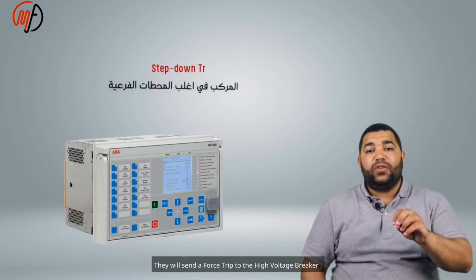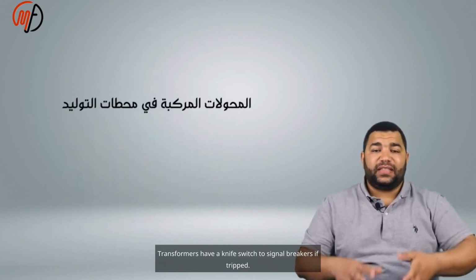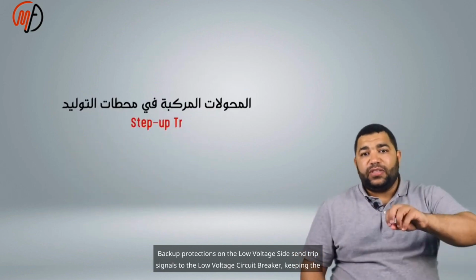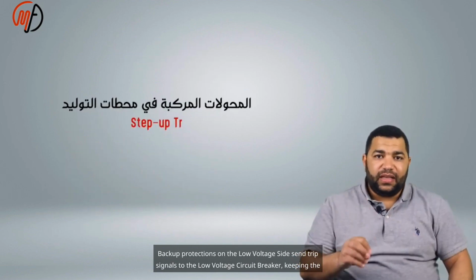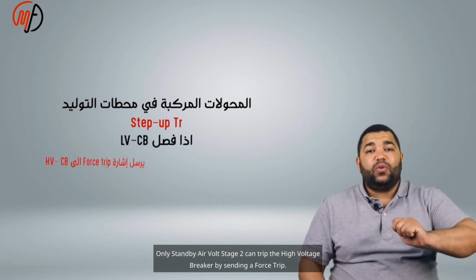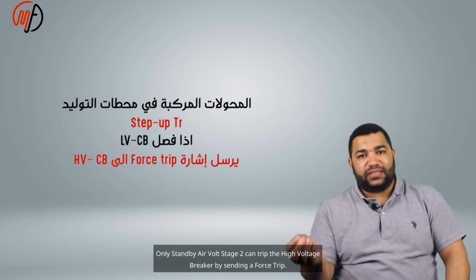They will send a force trip to the high voltage breaker. Transformers have a knife switch to signal breakers if tripped. Backup protections on the low voltage side send trip signals to the low voltage circuit breaker, keeping the high voltage breaker closed. Only standby earth fault stage 2 can trip the high voltage breaker by sending a force trip.